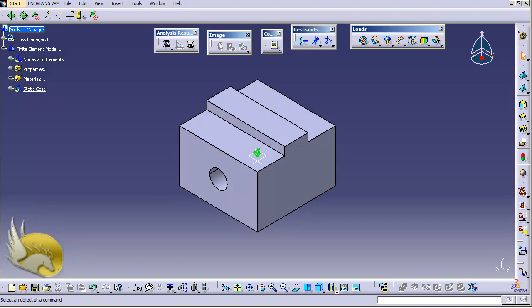And of course the storage. Let's find the storage. Storage is here, right here. And of course you can see apply material is available in this environment. I want to click on storage. And by clicking on storage and clicking on analysis manager, let's have this storage type here. Different types of storage are available. And I can tell CATIA where to store anything.